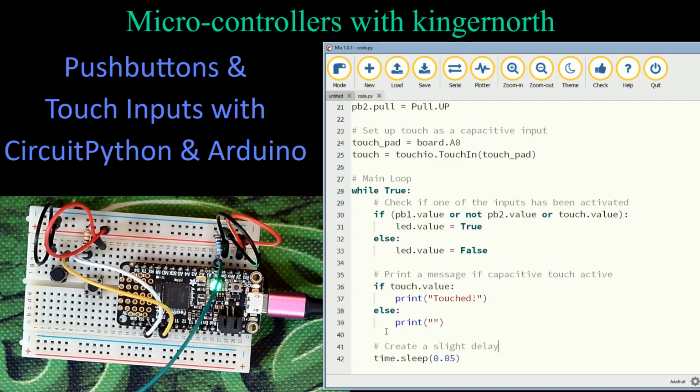The same thing goes true on the Arduino board. Any of those analog inputs can be used as digital pins as well. You can use them as digital input pins on the Arduino for the analog ports as well. So we do have some choices on what to do here. It saved us one pin because the generating signal is already built into it, so we didn't have to play with that. But everything else, it basically works the same way.